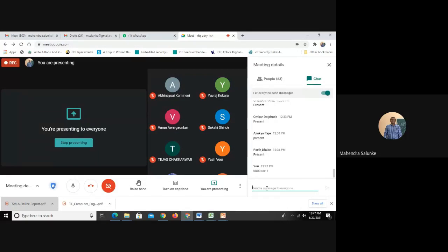Now if I am shifting it towards left, so ultimately, what is going to happen? This MSB will be taken out, so it will be moved into the carry flag. And in case of shift operation, 0 will be inserted from the LSB side. So from the right side, as we are shifting it towards left, 0 will be inserted.